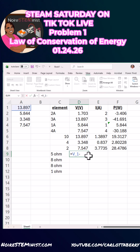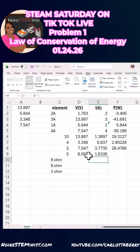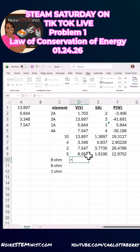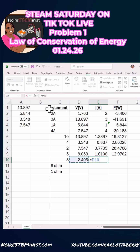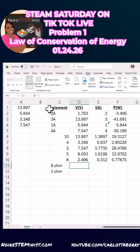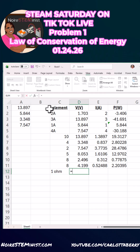Then V1 minus V3 is the voltage across the 5 ohm resistor. So then we're going to find that voltage and use that to find the current, and then that's 12.97 watts. Then for the 8 ohm resistor, the voltage is V2 minus V3. We're going to find the current, and then the power is 0.77875 watts. For the other 8 ohm resistor, the voltage is V4 minus V3, which is 4.199. Then we find the current, and it absorbs 2.2 watts.